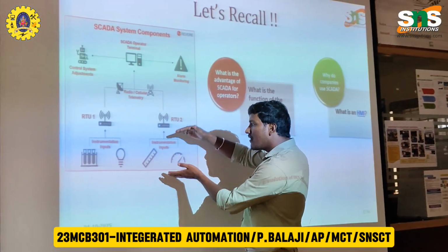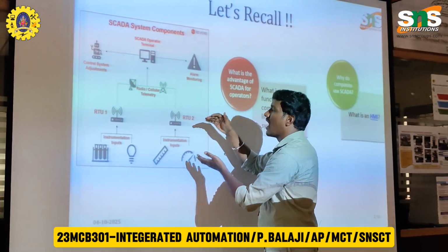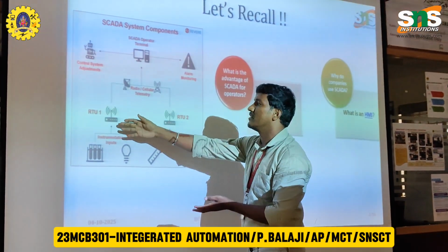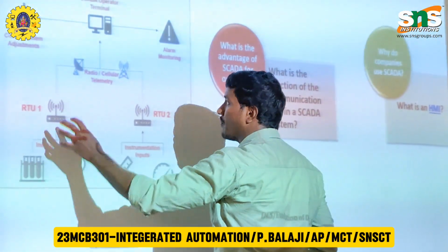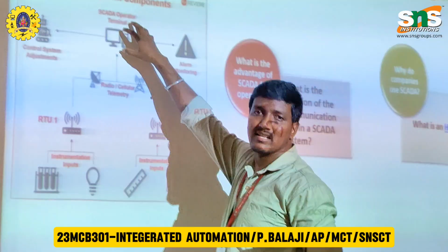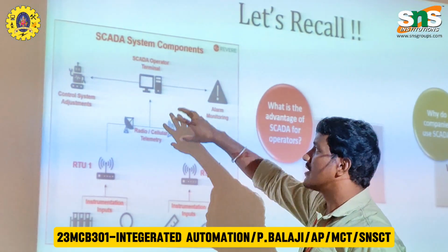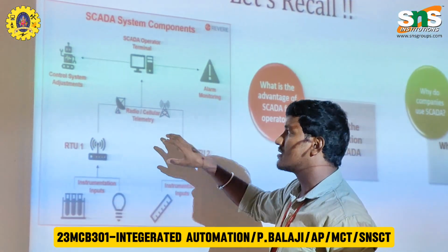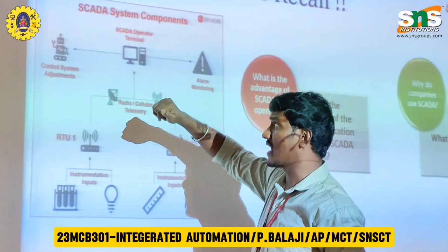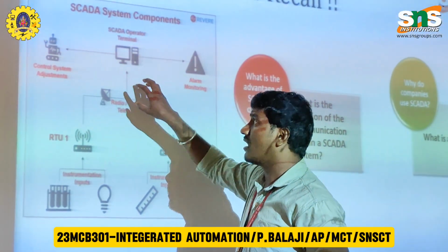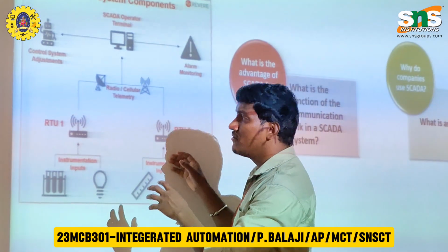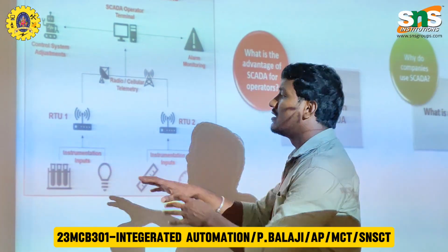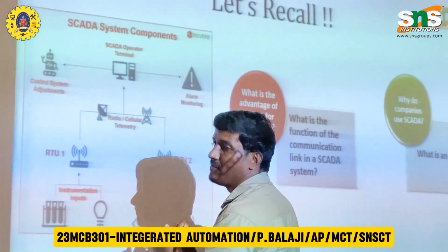By fetching the data from our actuating devices to the PLCs, or RTU, we can control the entire operation by commanding from the SCADA system. The data from the RTU and PLC goes to our SCADA system, and by checking that data, we can give commands to our RTU and PLC. By using the RTU and PLC commands, all the actuators will work.